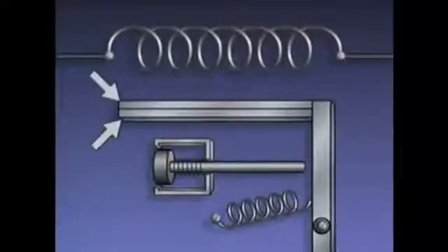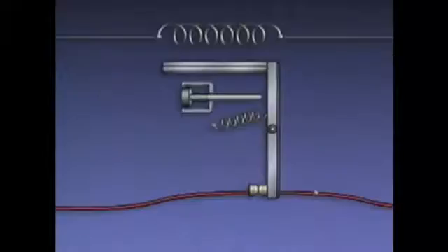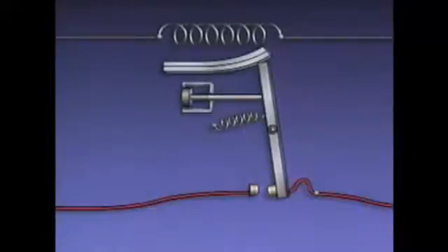The two metals in the bimetallic strip expand at different rates when the strip is heated by the heater. Under normal circumstances, the bimetallic strip holds the mechanical linkage in place, keeping a set of contacts closed so that there is a complete path for current to flow to the motor controller's M-coil. When the current level in the power circuit exceeds the rated value of the overload device, enough heat is generated by the current flow through the heater to cause the bimetallic strip to bend so that it releases the mechanical linkage. The strip bends because the two metals in the strip expand at different rates.